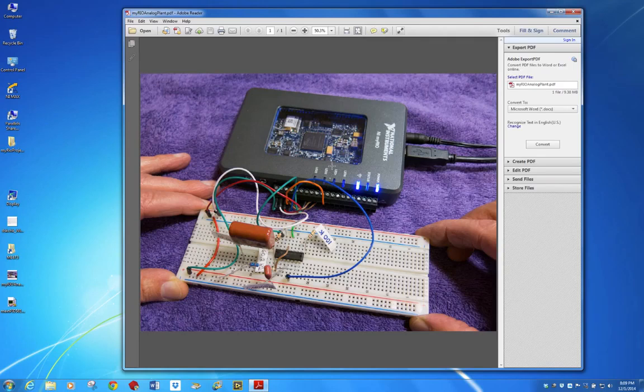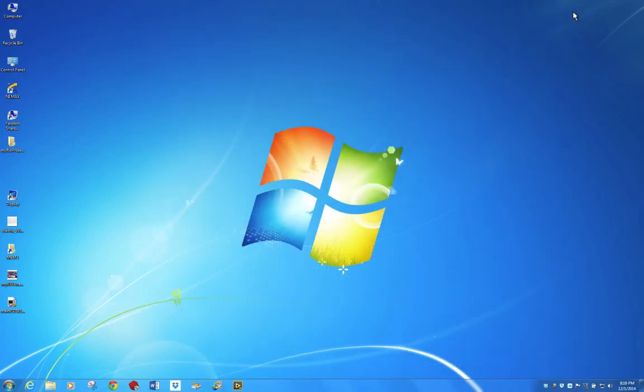Specifically, I have wired the MyRIO's analog output channel 0 to the input to the analog plant, and I have wired the output of the analog plant to the MyRIO's analog input channel 0, and I have used the MyRIO's plus and minus 15 volt pins to power our op-amp chip. So that's my physical setup.